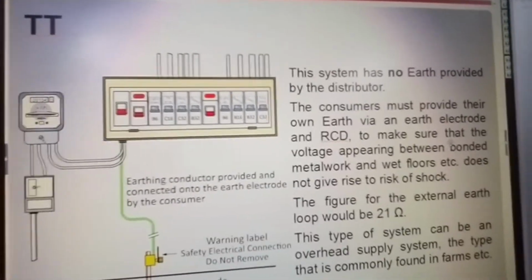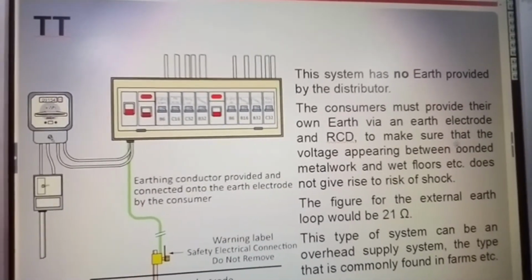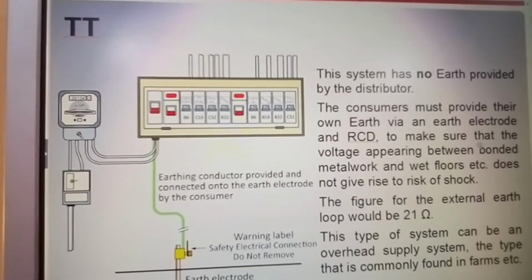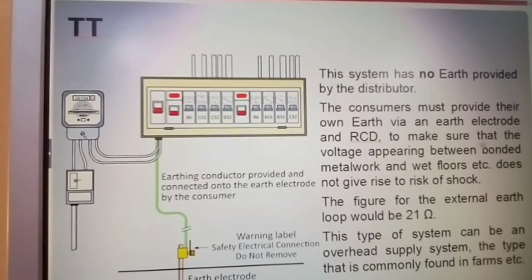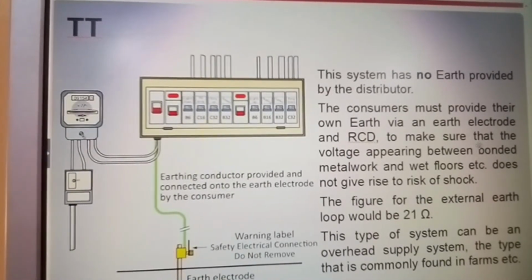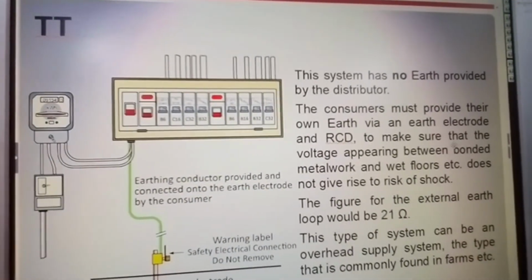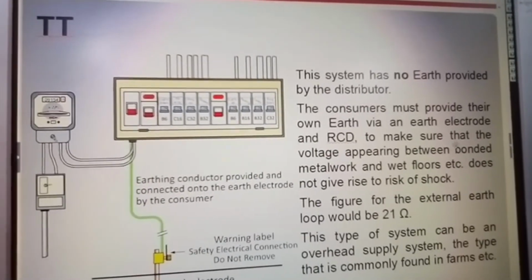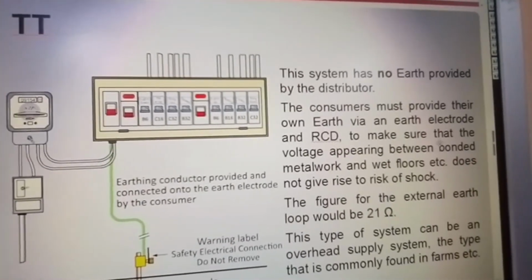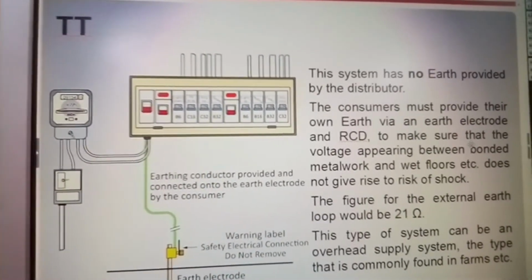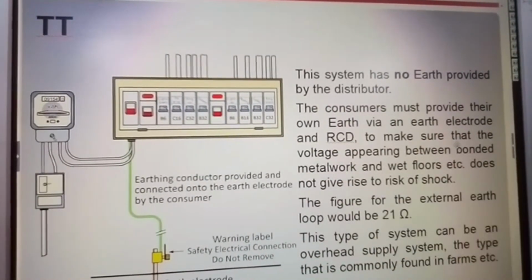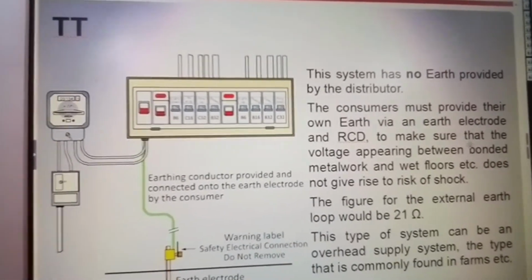Normally we used to put in a copper plate, so you'll find that sometimes you would solder a copper plate and set it into the ground. Basically it'll be about 12 inches by 12 inches, a copper plate set into the ground. But bear in mind the IET regs, what they stipulate and what they tell you that you need to be doing, and that is your Bible that you need to comply with at all times. Again, safety, safety, safety. And that's our TT system.